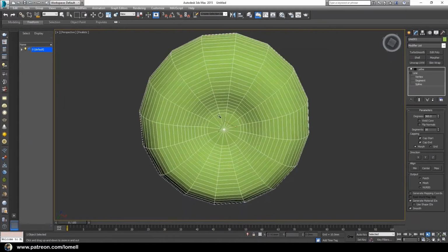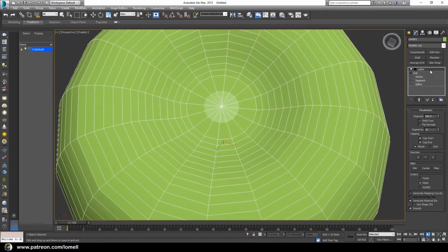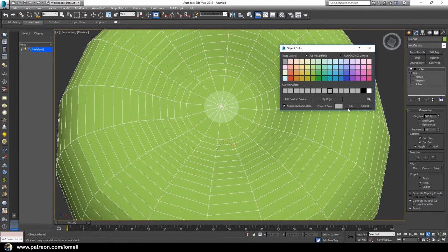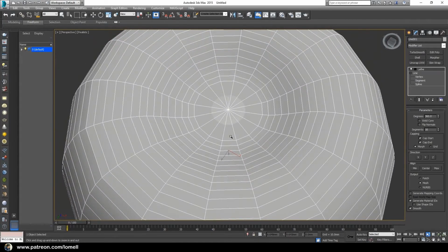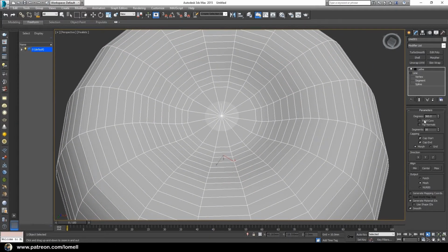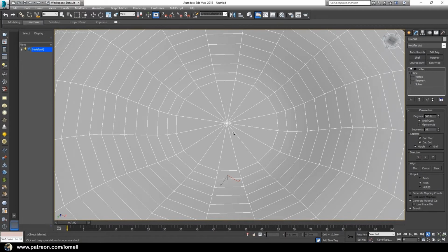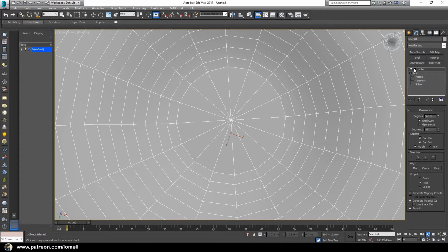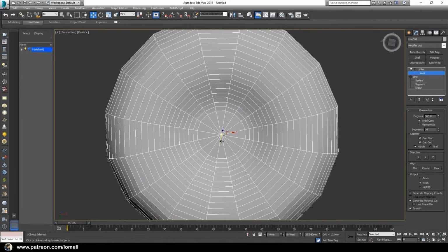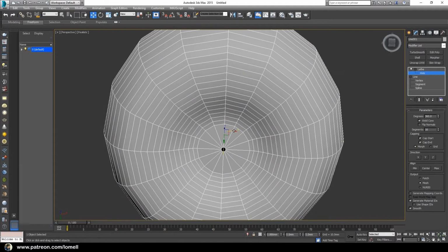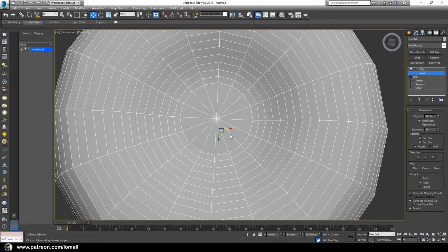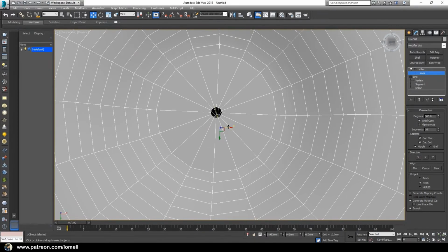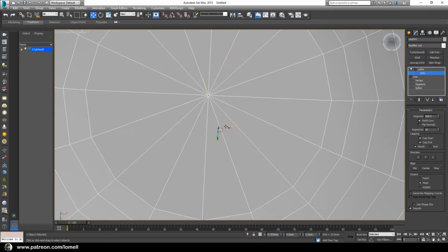and let's check if everything goes okay in here. And I'm gonna change it into a gray color so that we can see clearly what's happening in here. And make sure that you check the Weld Core. Okay, and it's gonna fix those surfaces in here. And if you see some holes happening around here, just go on to Lathe, expand this Lathe, and activate this Axis and try moving its axis towards the x-axis, and try dragging it a little until those holes won't show up anymore.